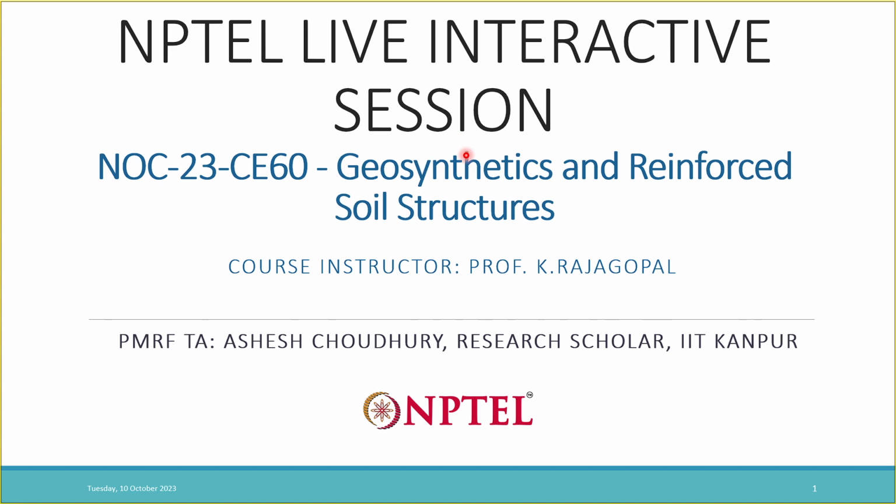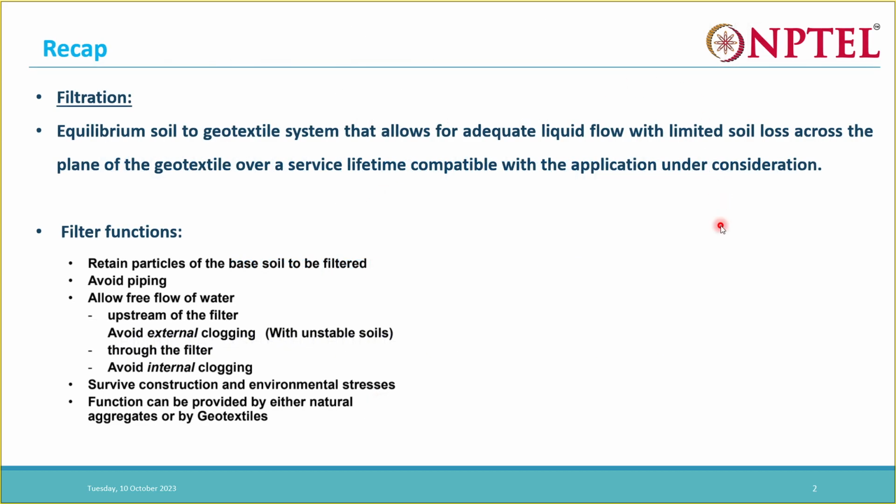So let us see what we studied. We already studied how to design a filter. Filters prevent the passage of soil and allow water to pass through. That is the basic purpose of a filter: to retain soil particles and allow free flow of water.